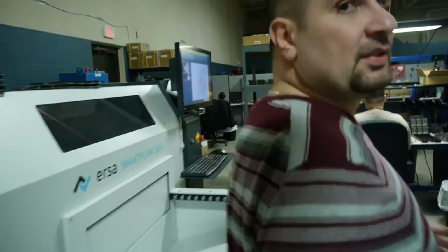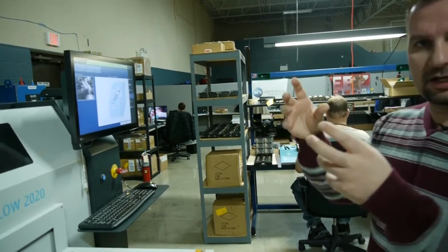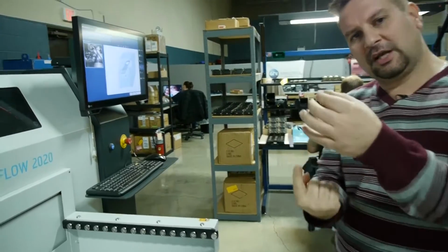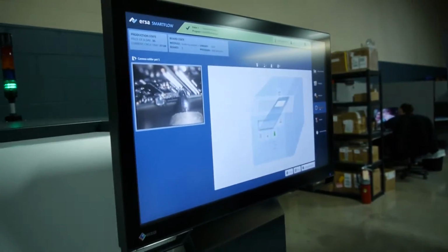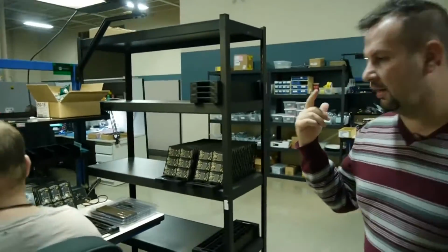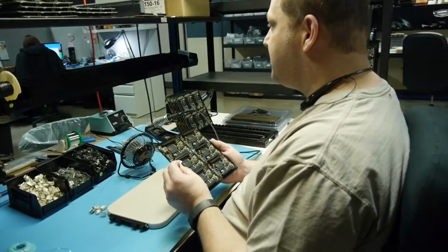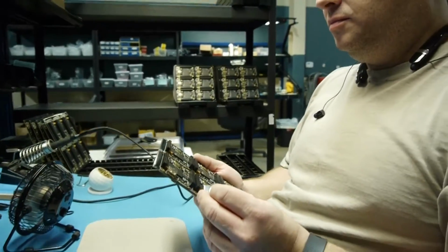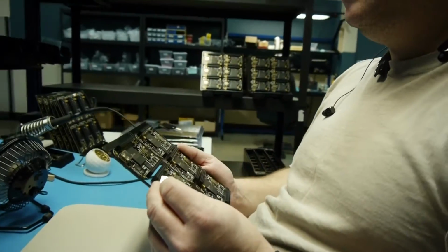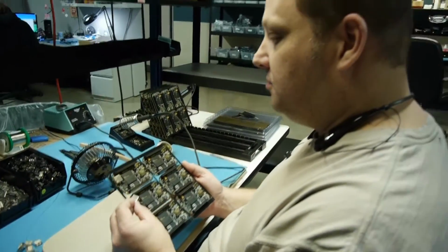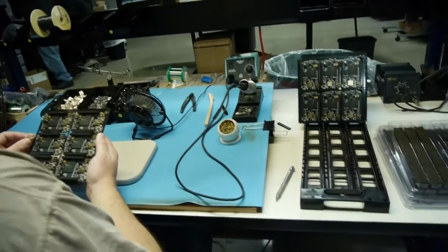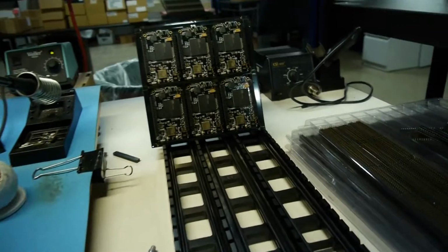The through-hole components are put through holes, and these go through a machine that has a solder fountain, if you will, that goes under the circuit and places the solder on the circuit board. And over here we stuff the circuits. Obviously, the machine does not place the components on the circuit. We have to manually stuff the components onto the circuit, and then once it's fully stuffed, we can take the circuits and place them inside the machine that will place the solder on the pins.